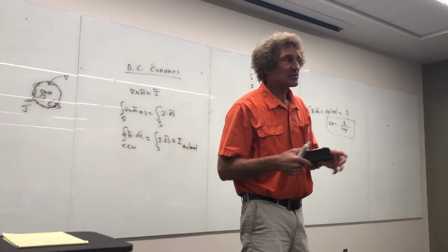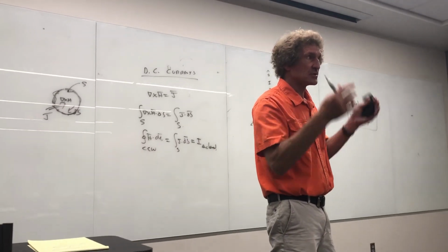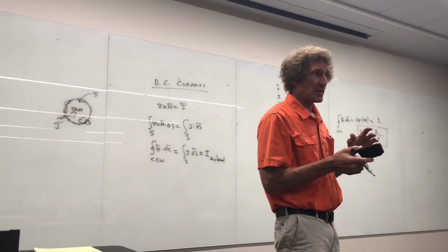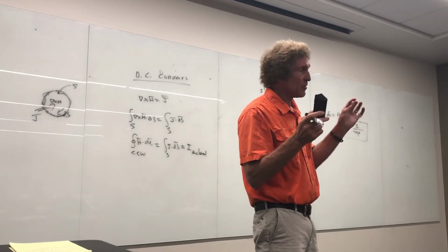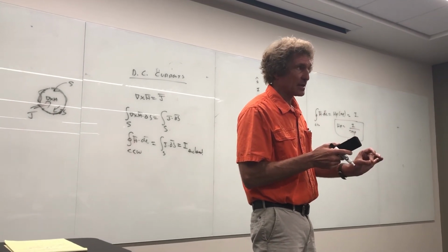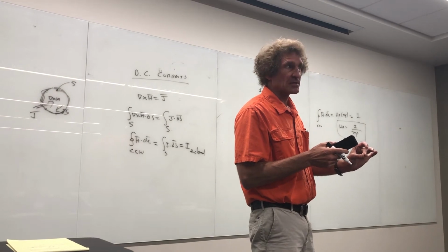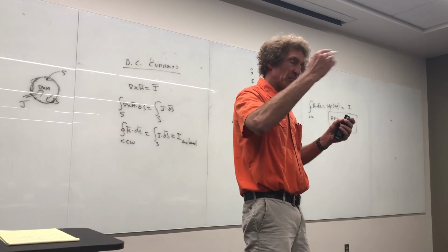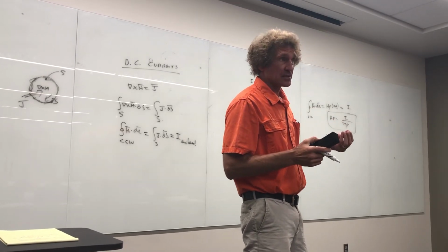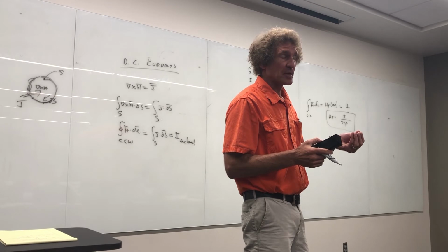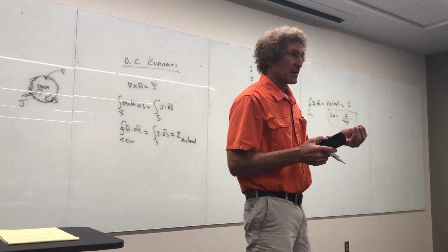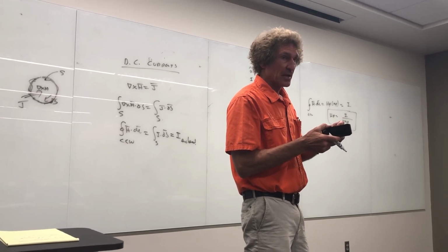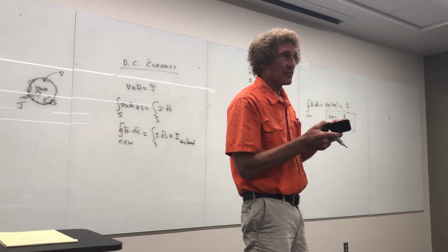Now, why is that so interesting? Because spherical capacitors can discharge faster than anything. If you charge up a spherical capacitor and try to discharge it, it's only limited by the inductance of the cabling connecting it. There are no internal limits. Most capacitors, parallel plate, or parallel plates wound into cylinders, have an internal inductance that limits the rate you can discharge them, but not a spherical capacitor. The only thing that limits them is the inductance associated with the connecting leads. And that's very interesting if you want peak pulse power.